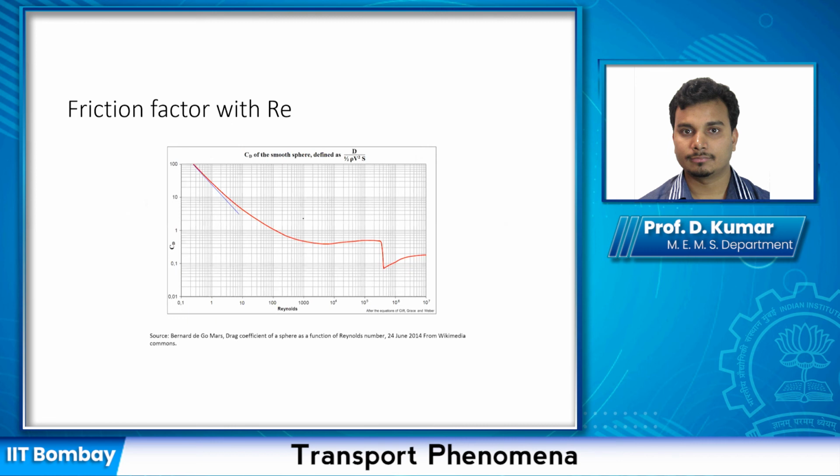So typically, similar to what we had for friction factors for flow through straight tubes, we also have a similar thing for a sphere, and a similar graph is also available for cylinders. You can check it. This corresponds to Stokes law, and you can see that even up to Reynolds number equal to 1 there is a small error, but you can use it with that limitation on accuracy.